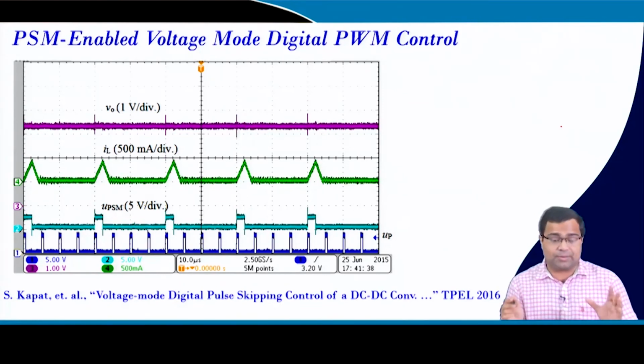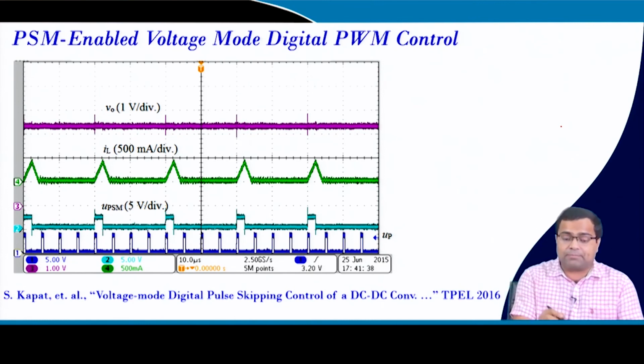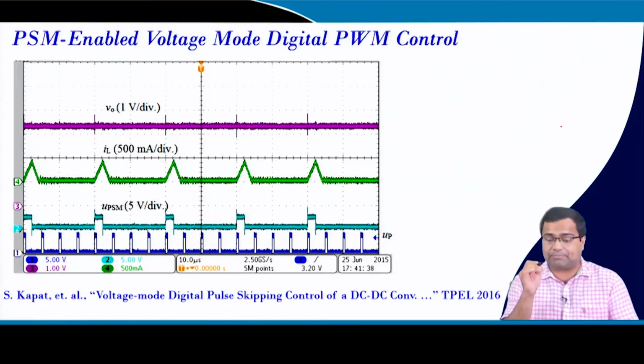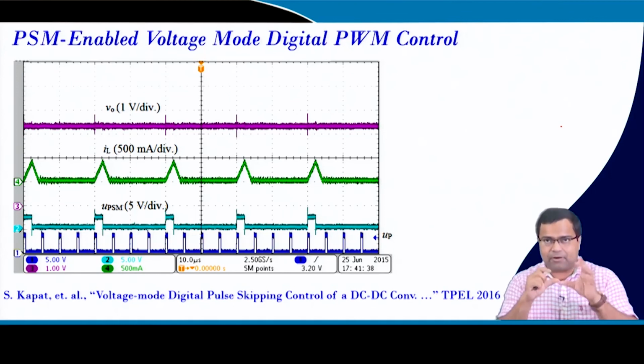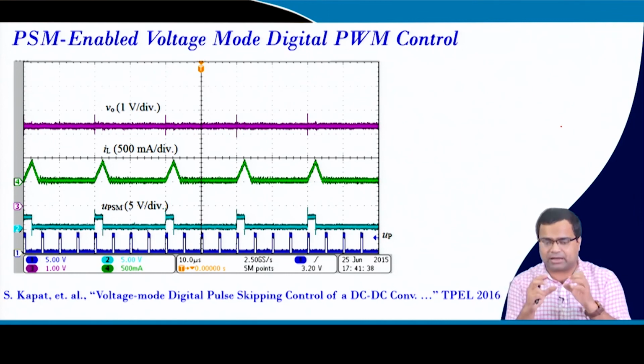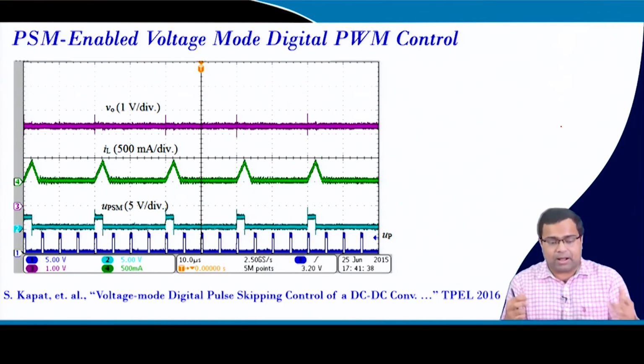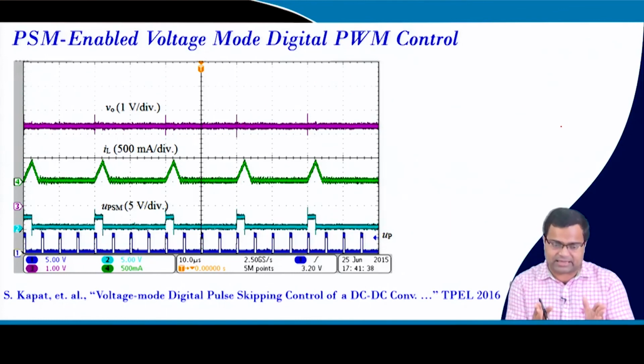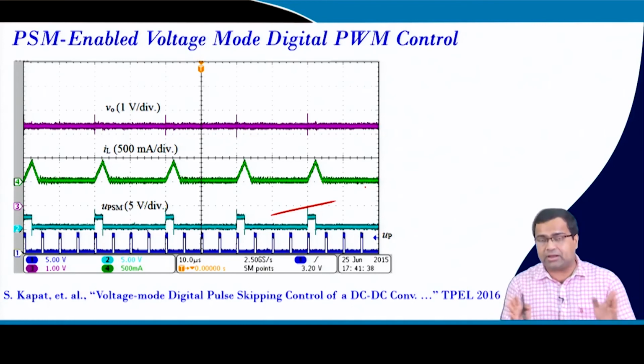The other technique we have also proposed is that you can reconfigure the voltage control pulse skipping mode, where the number of charge and skip pulses, because we saw in pulse skipping there is a non-monotonic spectral composition, that means the waveform was not repeating in every cycle, there are slight changes and it will create some kind of high periodic behavior. But if we can configure the number of skip cycles and charge cycles, in this technique you can set it a priori, by which you can optimize the energy, efficiency, and you can achieve perfectly periodic behavior.